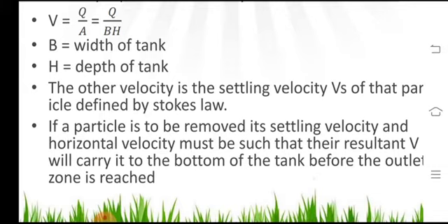In this case, the perpendicular area will be explained in terms of the depth of the tank as well as the width of the tank. It will not include the length of the tank, because the movement is supposed to be perpendicular to the area. So that area which will be only facilitating the movement of the entire volume of the wastewater will be included in this